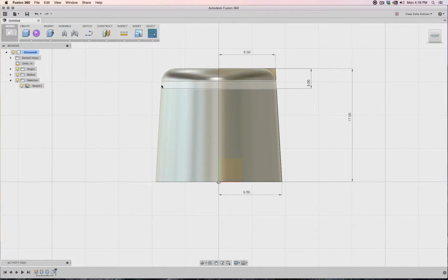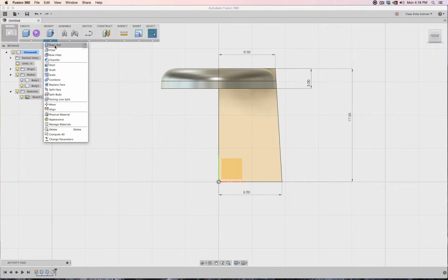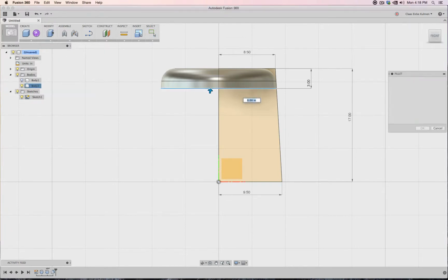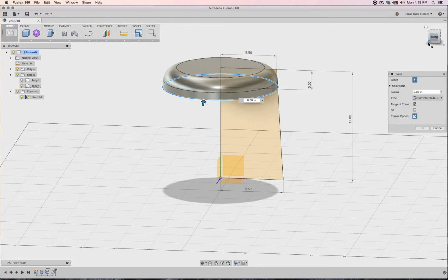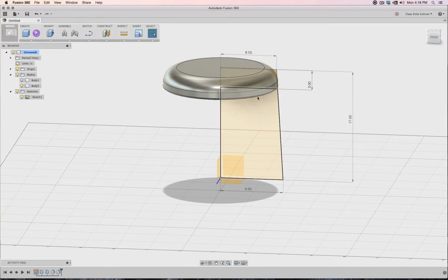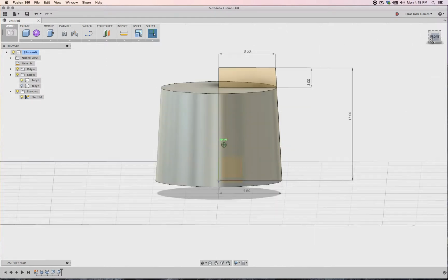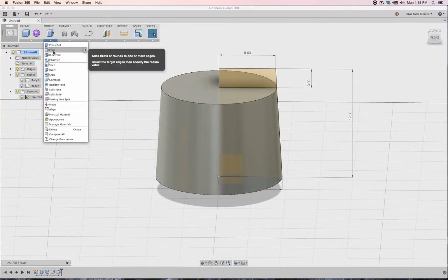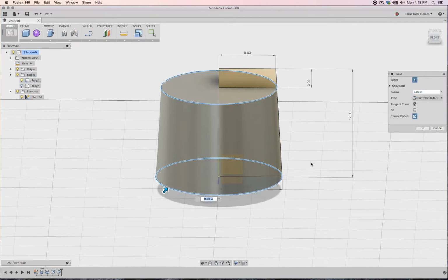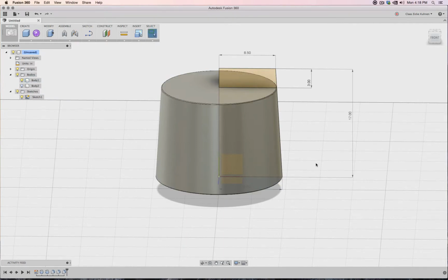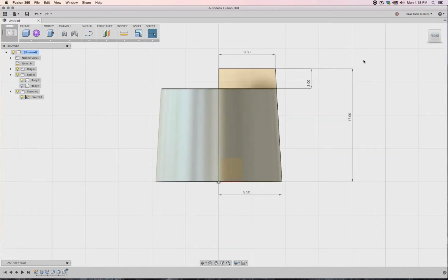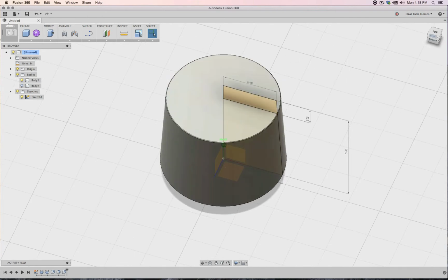So let's say this is all upholstery and this is wood. So these parts are not razor sharp edged. So I'm going to select this one and say fillet this rounded part, maybe by 0.25 inch, let's say. I'm making this a little bit bigger, so simply you can see the difference. And then I go to my wood part and say also here fillet you and you, maybe 0.1 fillet. So just slightly round. Okay, that wasn't too difficult.